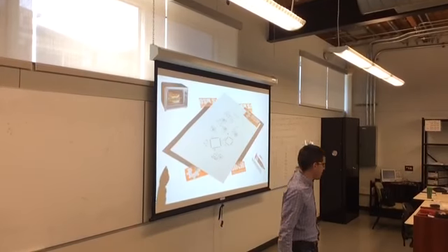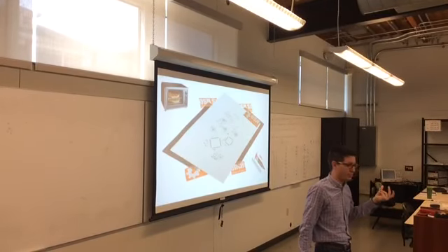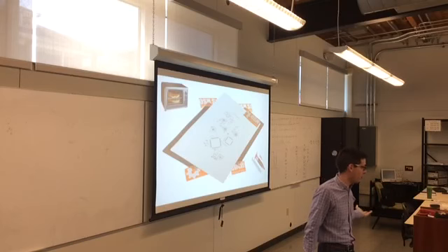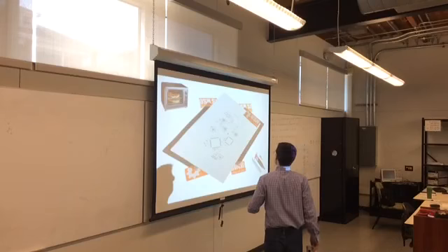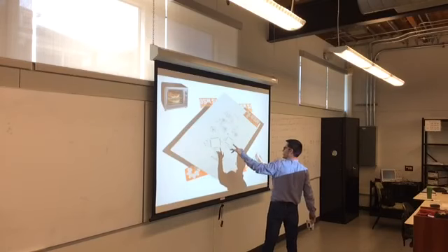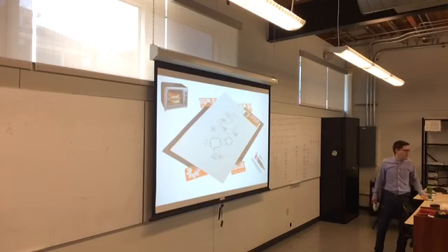The solder mask will make the solder kind of bubble up on the pad, but if you put a ton of stuff on there, it's still going to overflow. There's not going to be enough surface tension to hold it there. So this is a hugely complex design. There's a lot of components on that design. Yours wouldn't be that complicated.